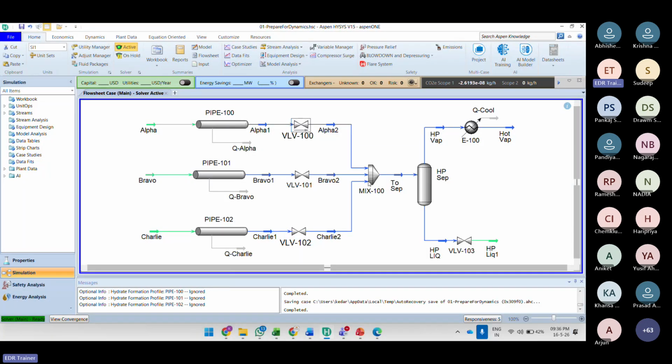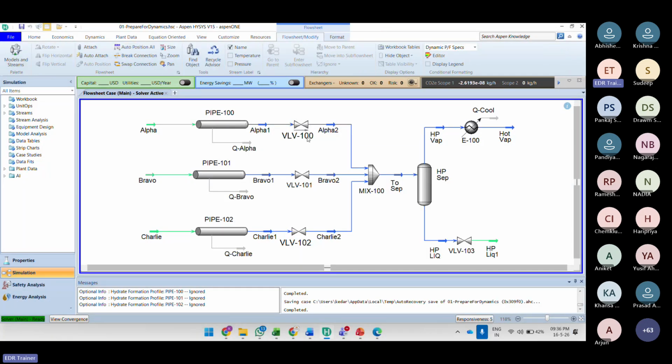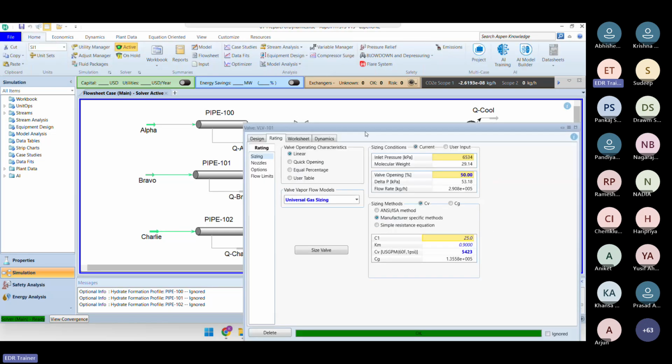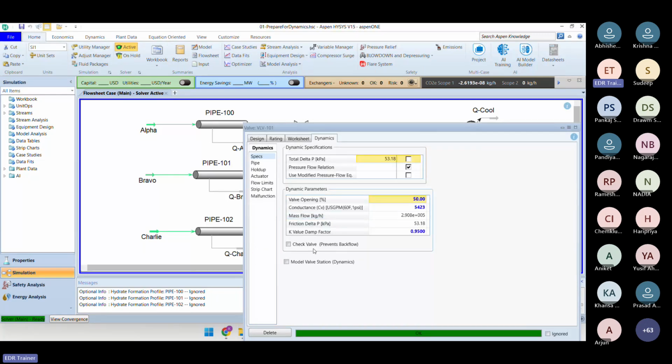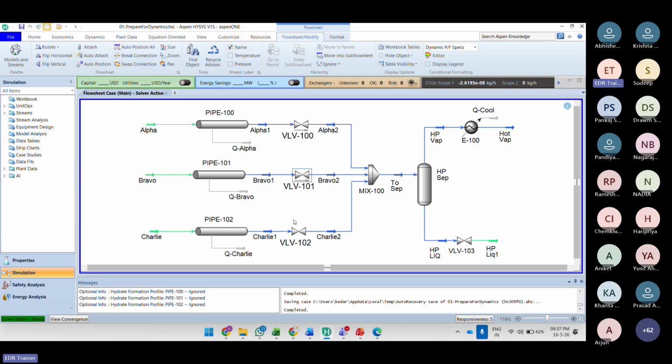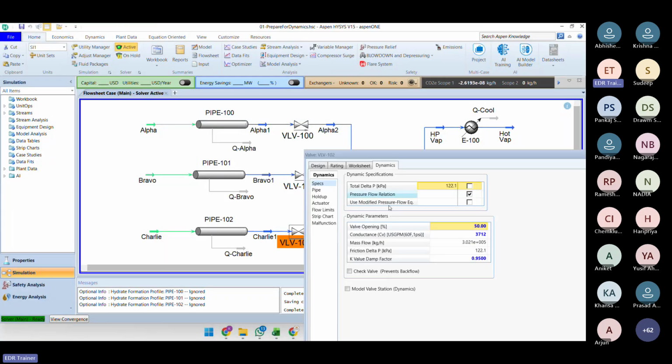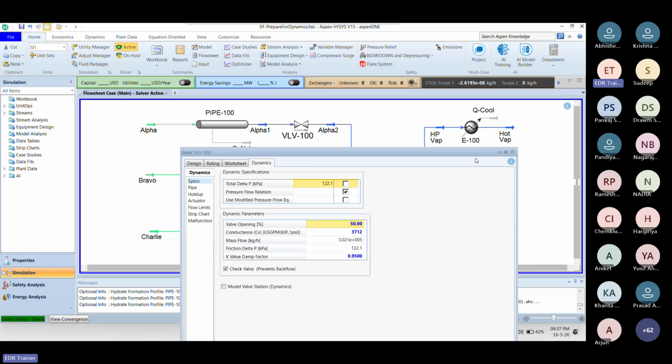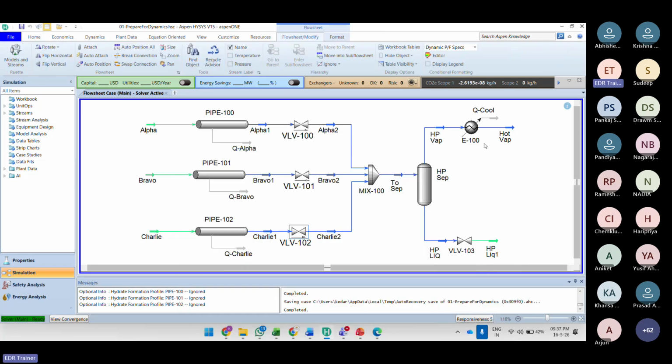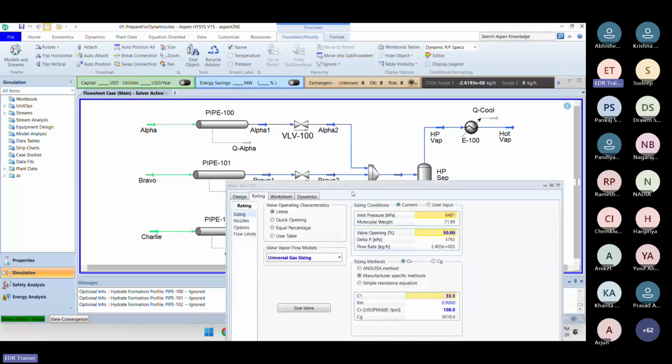Once you put a check valve there, the reverse flow will not happen through this valve. In the same way you can go into the dynamics and use a check valve to prevent any backflow. If that arrangement is there in your system, do that. Otherwise, you keep it like that, and if reverse flow happens, it is also an indication that you need to have a check valve.